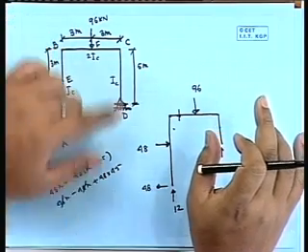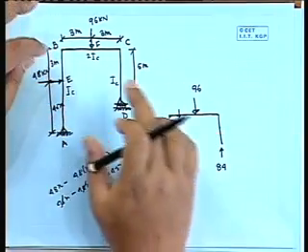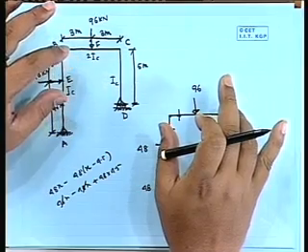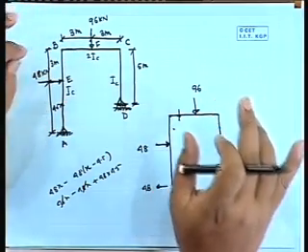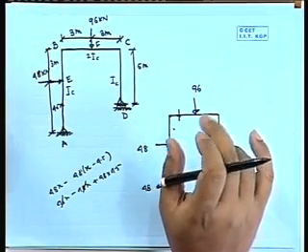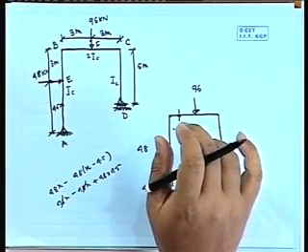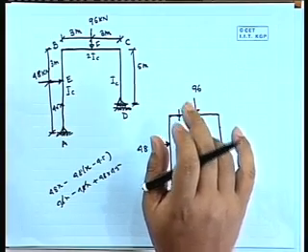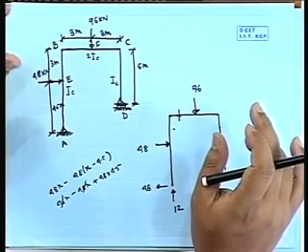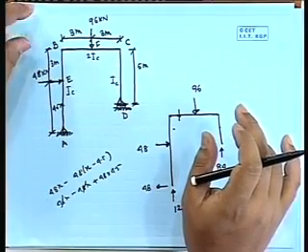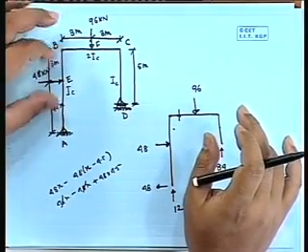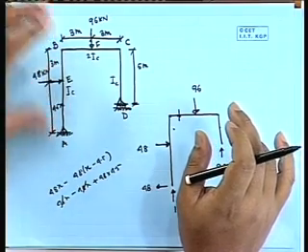So at A, B, C, D, slope will be there, plus at B and C displacement will be there, and the displacement at B and C will be identical, because at this level we are not considering the extension of the member. The axial deformation part is not considered at this level. So if B moves by delta along the horizontal direction, C will also move by the same distance, but there will be no vertical displacement. B will not come down or go up, because the extension of the vertical member we are not considering.